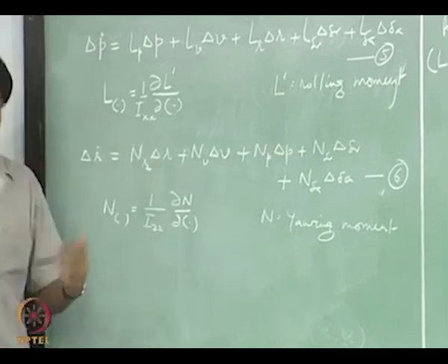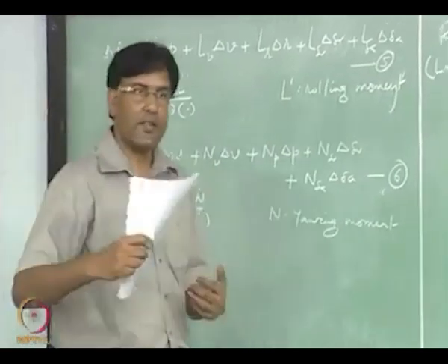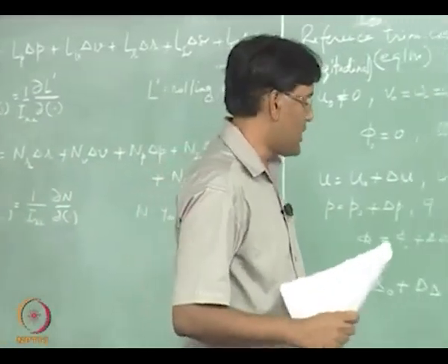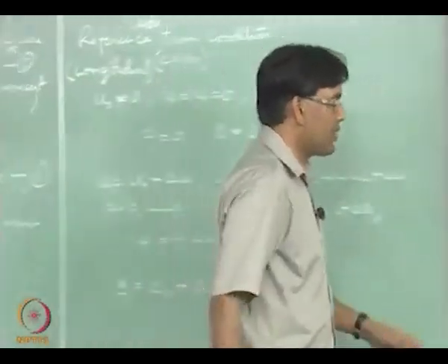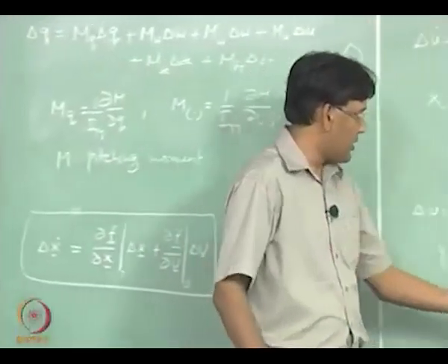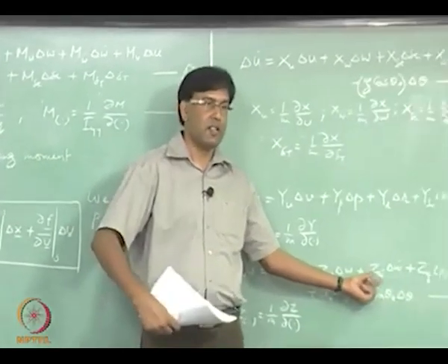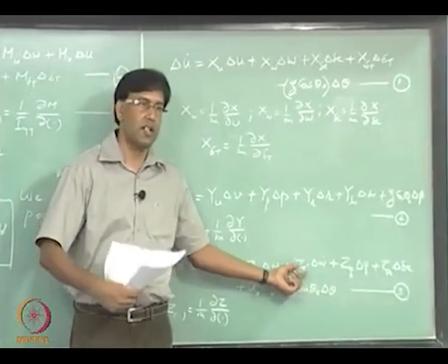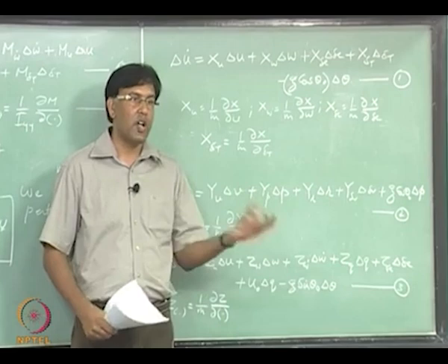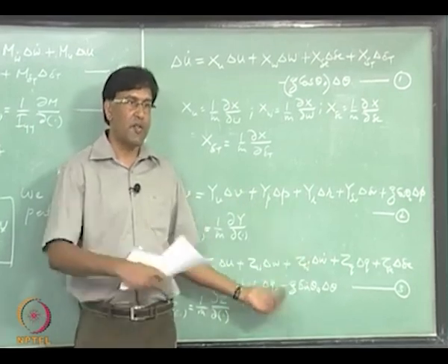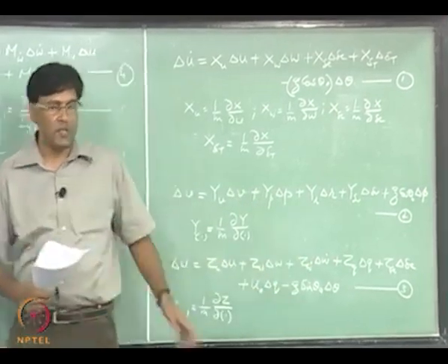Remember to simulate the accurate motion of aircraft. If my wind tunnel measurements give me this as I am measuring, and this is not a small value, then I have to include that in the equations of motion.